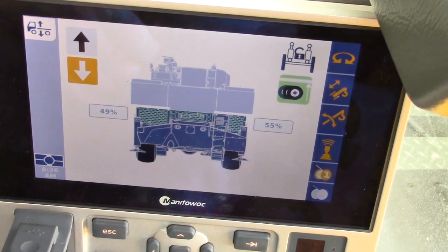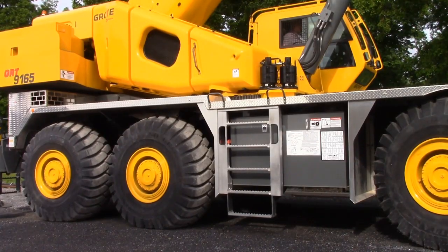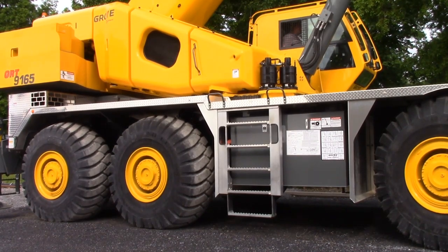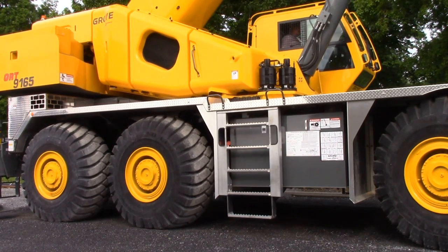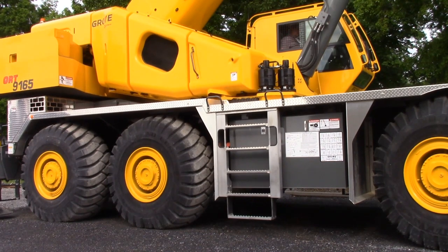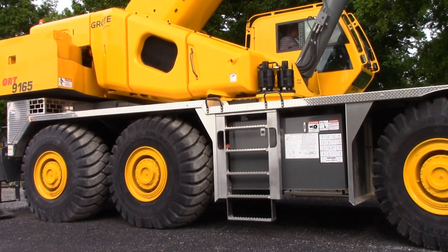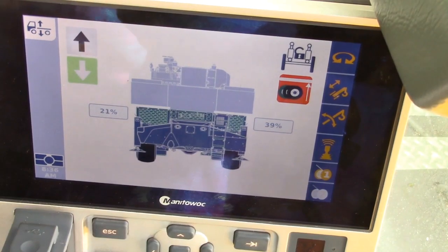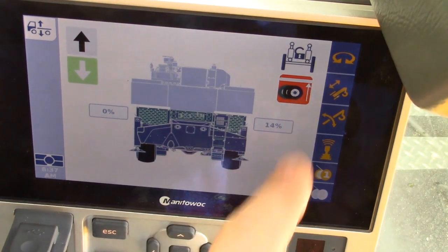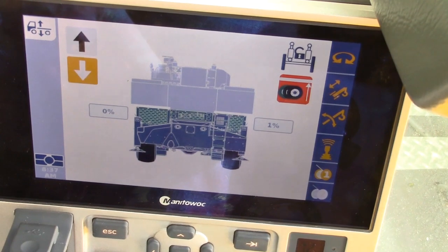The first condition you will see is when transporting the machine, you should lower the machine completely to 0. This feature has been added to the crane for height of loads and easier transportation. By selecting the down arrow, we will see and hear the suspension drop. Notice when we fall out of tolerance, our not at ride height symbol becomes red and active. The crane now can be loaded on a truck and moved to the next job site.